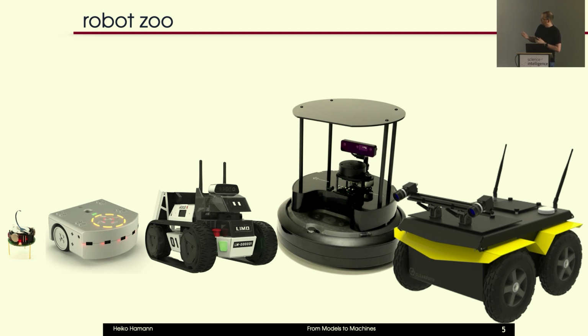It has a LiDAR, a laser scanner, and an RGBD camera, and with that you can already do state-of-the-art methods. Something like SLAM, for example, simultaneous localization and mapping, a standard thing in robotics. And this is the Jackal robot from Clearpath Robotics in Canada. This is already a bigger robot. It can also go a little bit off-road, 17 kilos, and this could also move around on campus. I'm not sure what your campus really looks like, but maybe a more traditional campus.